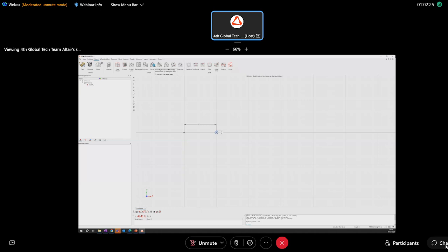And to create the air around, we can use again the circle by center and point tool, positioning the mouse at 0, 0. So click for the first time and then drag the second point, and click on the x-axis to create the circle. And again, the possibility to enter the diameter is available. So we can type 35, right? And press enter. Okay. And ESC from the tool.